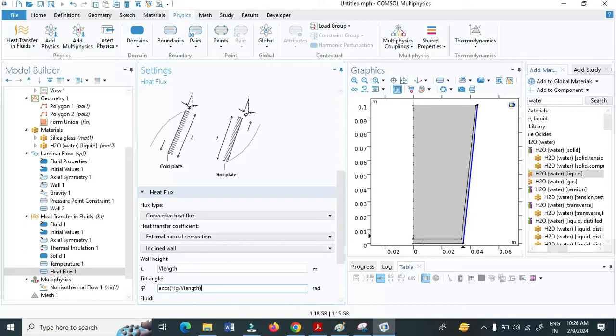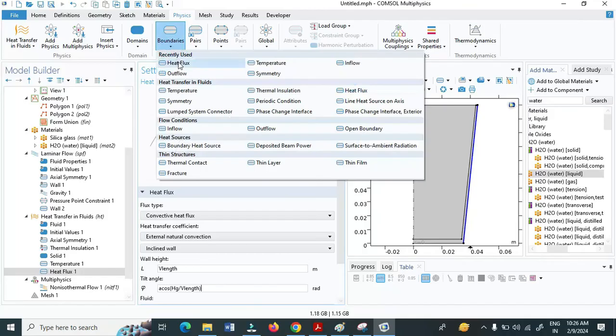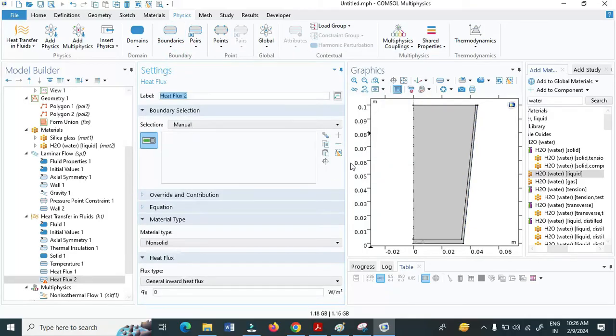There is a formation of an air layer at the top. So here, instead of taking a heat transfer coefficient, I'm going to take the conductivity of the air layer at the top as the heat transfer coefficient. So let me select one by one. What is the convective heat flux? Then let me select the H value as 2, that is nothing but the conductivity of the air layer at the top. And I need to select the boundary as well. That is my boundaries here, and they are small boundaries. Let me select them by zoom to select.